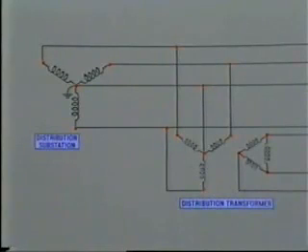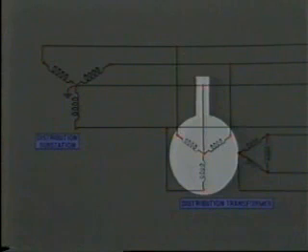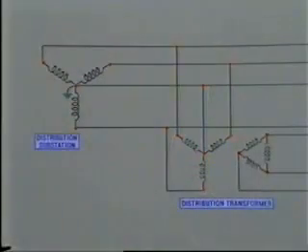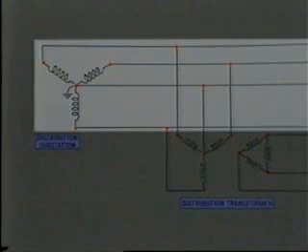The Y-delta connection is more common, but this brings us to another possible problem area. Suppose we have the distribution transformer primary winding connected in Y like this, and the transformer neutral is grounded by connection to the neutral wire or perhaps to a separate ground. The primary system here is the typical 4-wire system with a grounded neutral.